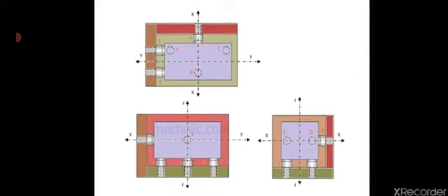position of these pins. The workpiece rests on 3 pins which are inserted in the base of the fixed body. The workpiece can't rotate about the axes XX and YY, and it can't move downward. In this way, 5 degrees of freedom have been arrested.